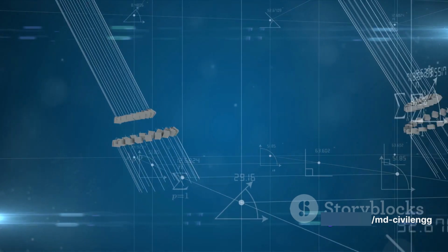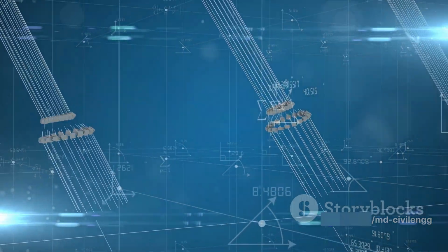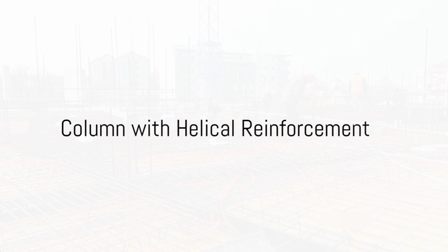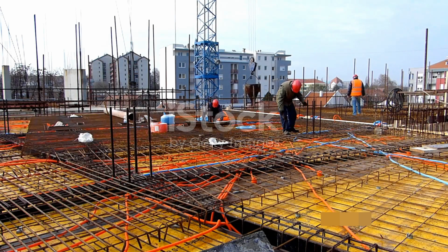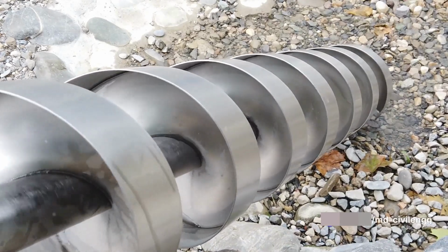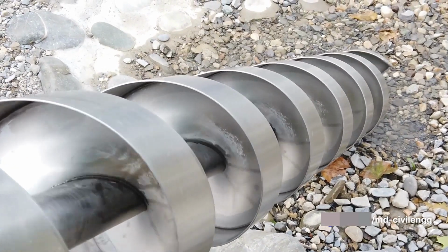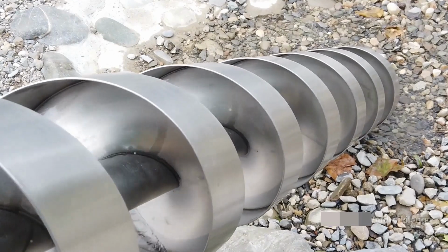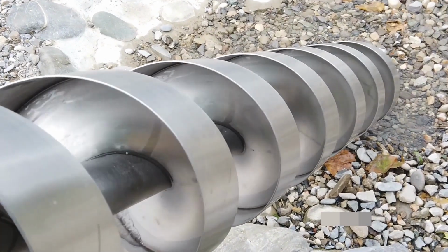This is another important aspect of column design, and we'll delve into it in the next scene. Helical reinforcement can significantly increase the load-carrying capacity of a column. Let's delve into that. Helical reinforcement, also known as spiral reinforcement, is a method where steel bars are wrapped in a helical or spiral pattern around the longitudinal bars in a column.